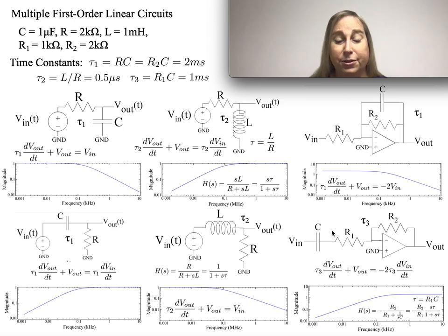If I think in Laplace terms, it's 1 over sC, which in frequency terms means at really low frequencies, this is a gigantic resistance. And remember, gain is this resistance over, well, effectively the series of these two. So as that resistance is huge, that's going to basically make my gain go to nearly 0.